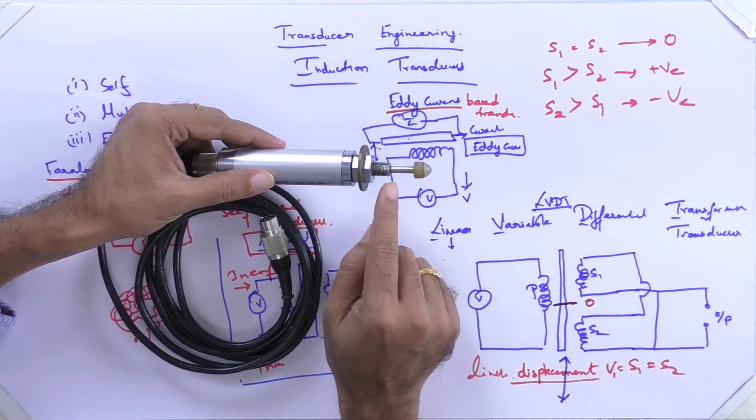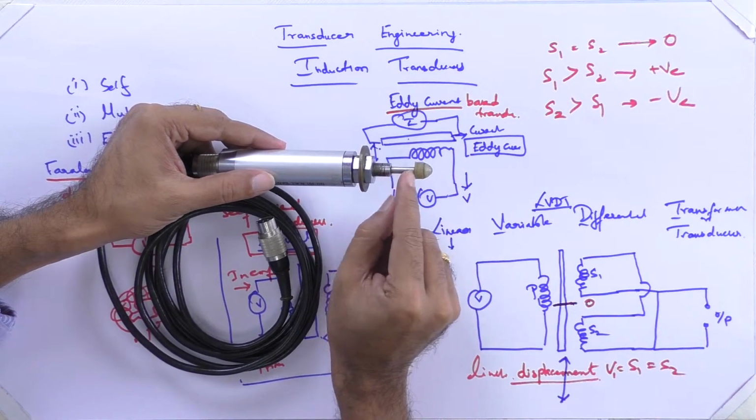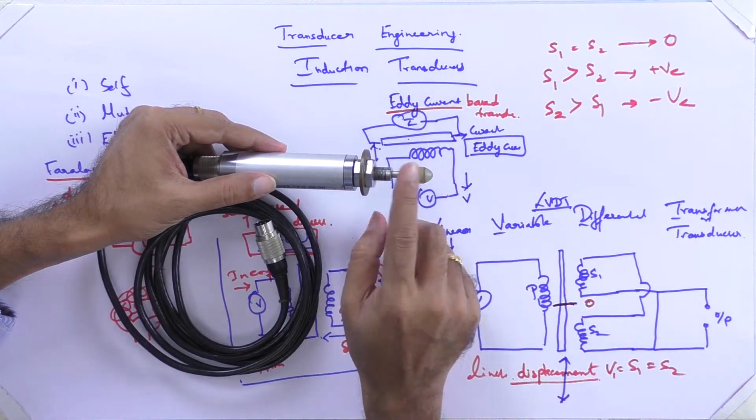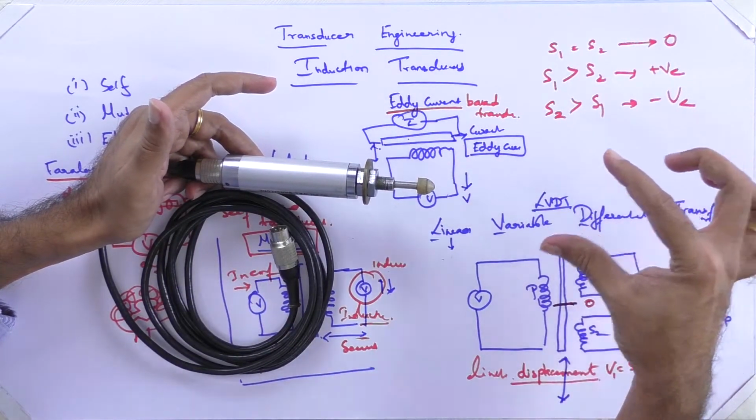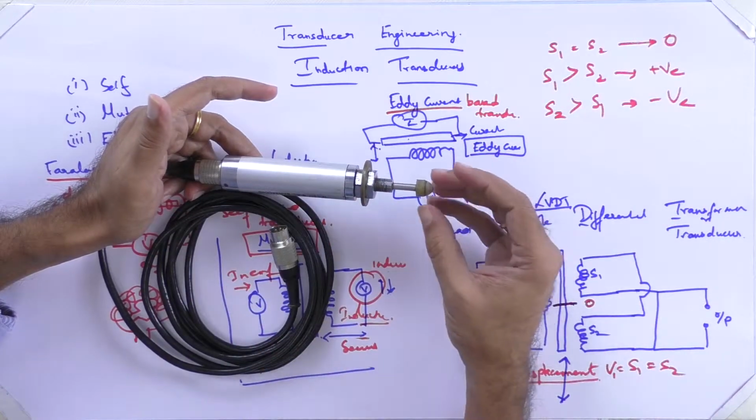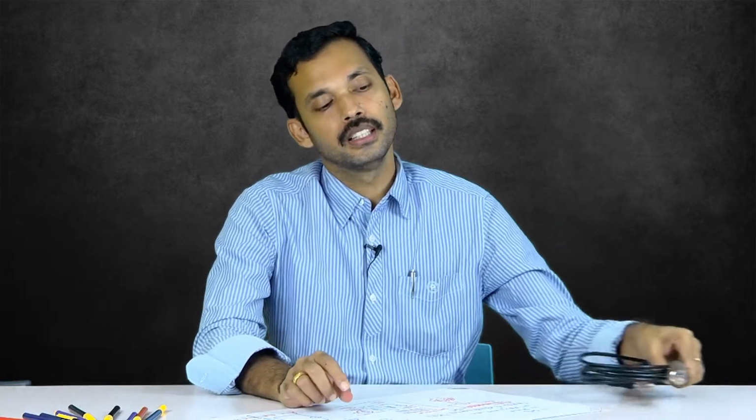But you can very well see here the maximum displacement is 1 centimeter; that much only you can measure with this. But depending upon the length of the LVDT, the shaft thickness and the materials, the properties may also vary. Okay, it's a very sensitive, very precise instrument that can measure in the range of below millimeters, or even at the micrometer level. So this is the main advantage of an LVDT, that is a linear variable differential transformer.